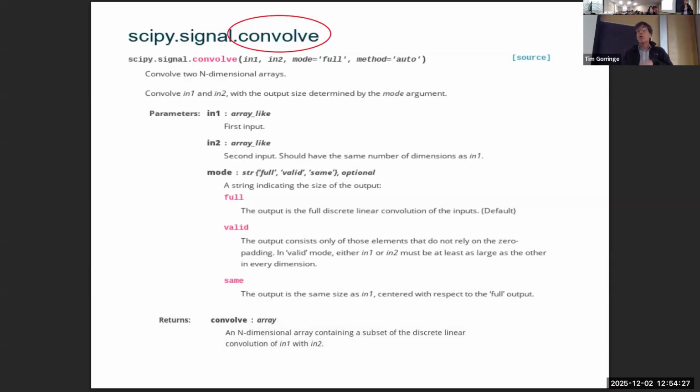So these are more computationally intensive, but what these more computationally intensive filters give you is a much greater discrimination between passing a signal and attenuating noise. The transition from passing the signal to attenuating noise is much sharper, much more defined. And actually the noise suppression is much deeper. So that's the advantage of them.